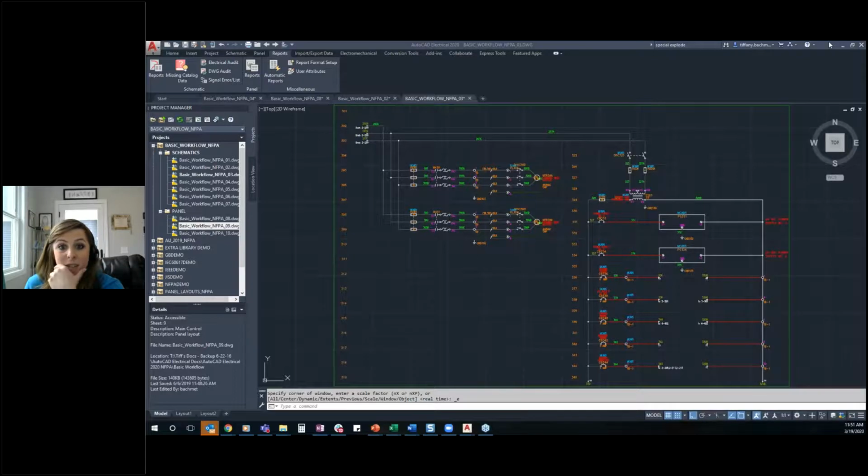Now, a lot of this stuff does live in Xdata because we don't typically have all those attributes sitting on panel, especially panel footprints. It just comes over crossed in as Xdata that lives on it, but that's all updated and connected to the schematics. There's nothing that you should have to manually edit on the Xdata.